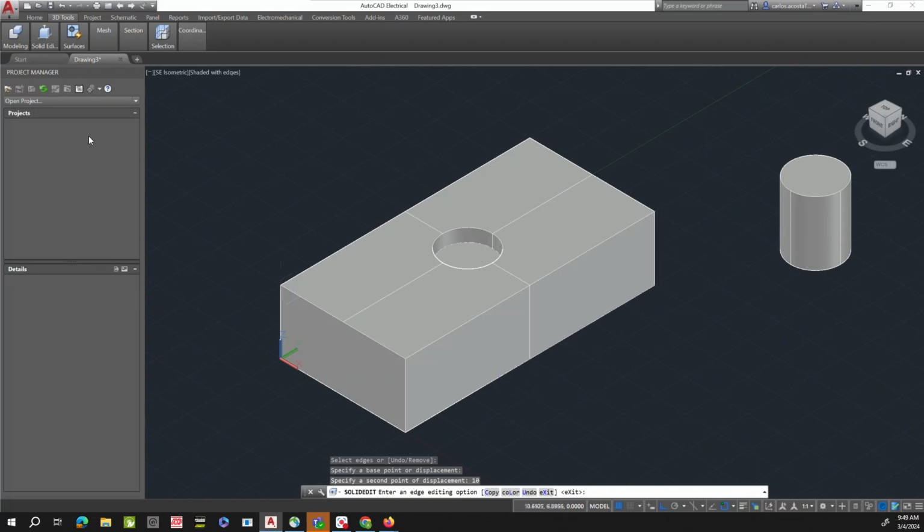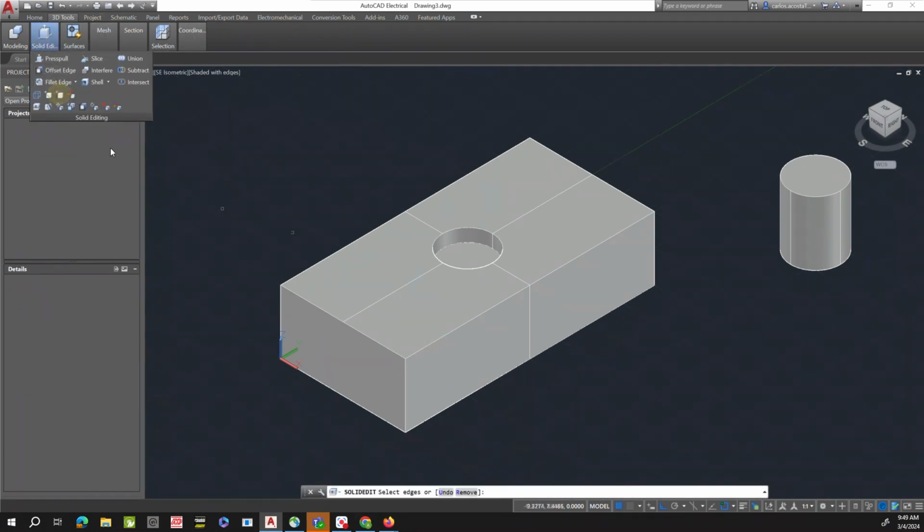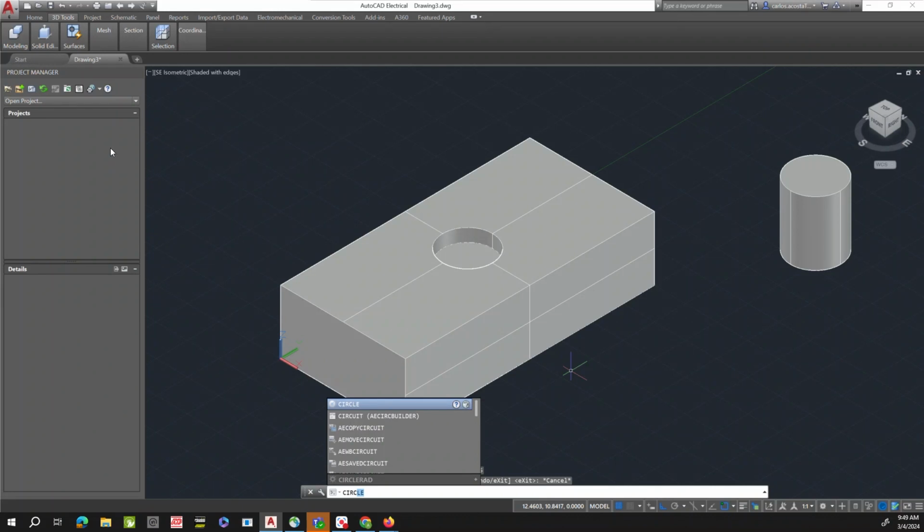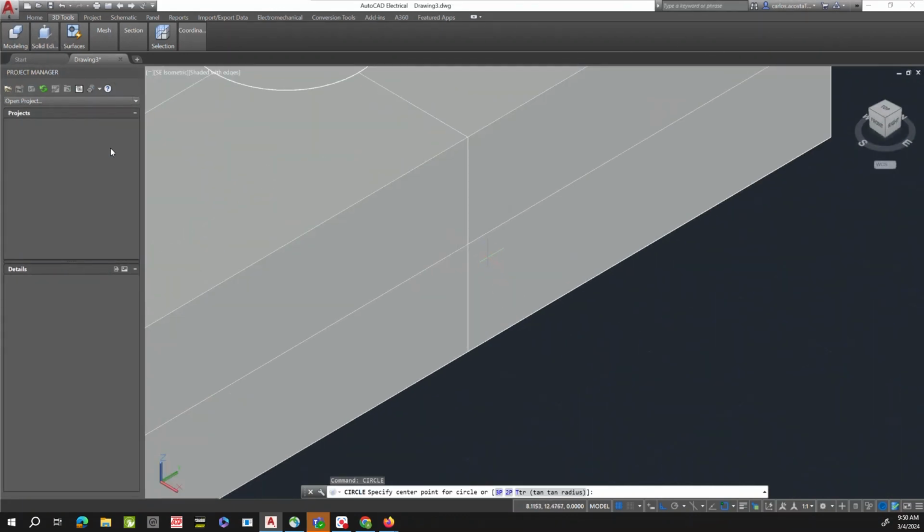And then if you do press pull again, you select this line. We have to select press pull first. Then we do this line, enter, from this reference point vertically down, but a distance of 5. Well, that was 5, so we're going to do 2.5, and then we're ready for another circle, or whichever shape you want to do.